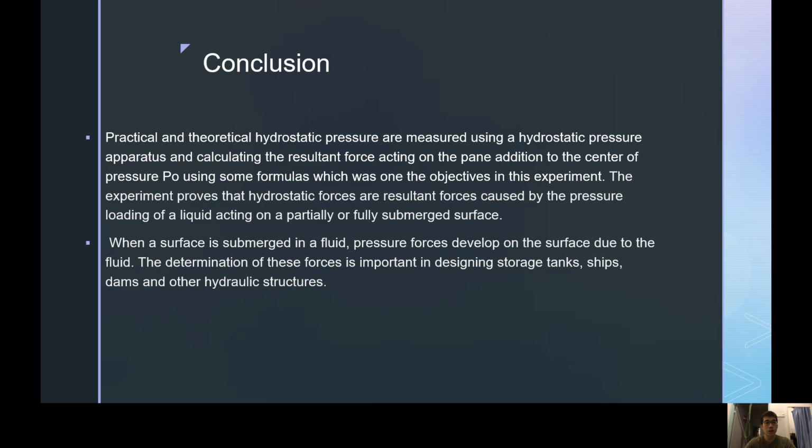Lastly, in conclusion, practical and theoretical hydrostatic pressures are measured using a hydrostatic pressure apparatus and calculating the resultant force acting on the plane, in addition to the center of pressure, using some formulas, which is one of the objectives in this experiment. The experiment proves that hydrostatic forces are resultant forces caused by the pressure loading of a liquid acting on a partially or fully submerged surface.